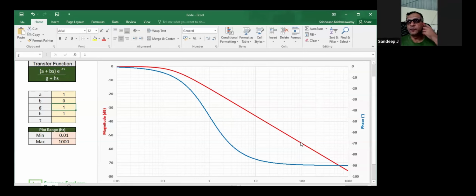I agree to a level. What you said is, yeah, when it is getting saturated, you start to see a lot of the bad nth harmonics coming into the picture. I agree with that. But the point is, you would not be running an amplifier in a pure class A mode all the time, without the crossover distortion. The reason I had to ask you this is that if we have a disproportionate harmonic structure, then you would lose the actual natural harmonic profile of the instrument which is being played.